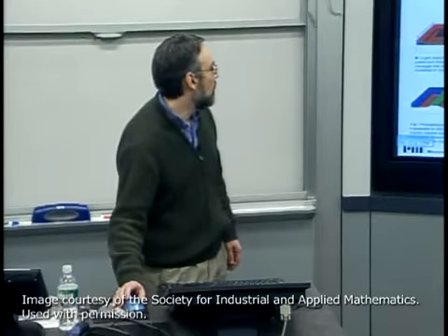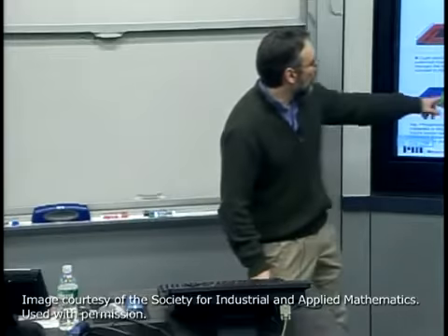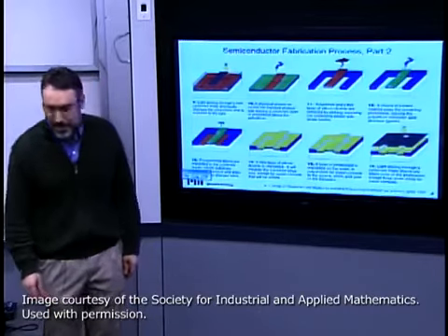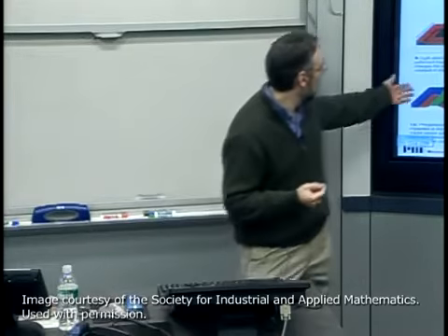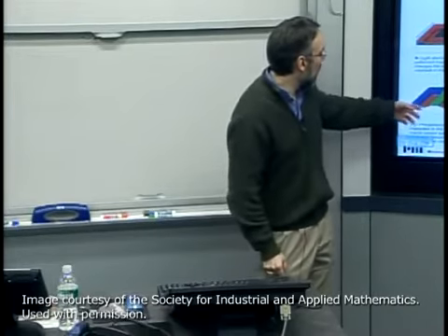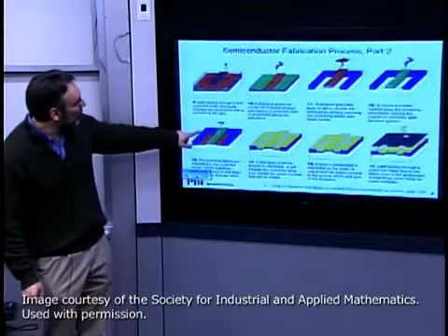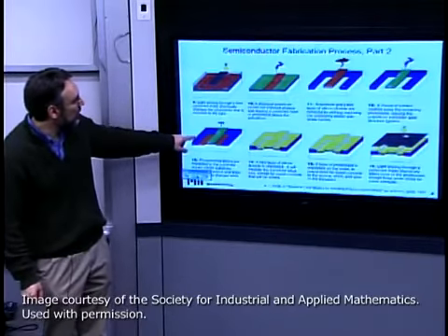Okay, we're almost there with this device because now we're primarily just repeating these same kinds of structures. What we're going to do now is another photolithography step here. Essentially, what we want to do with this yellow layer is build up an insulating layer. So I think a new layer of silicon dioxide is deposited. In this case, it's not thermally grown through that chemical reaction of oxide and silicon because I've already got polysilicon. I've already got a very thick layer of silicon.